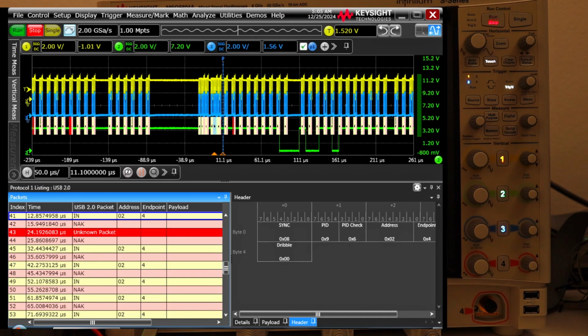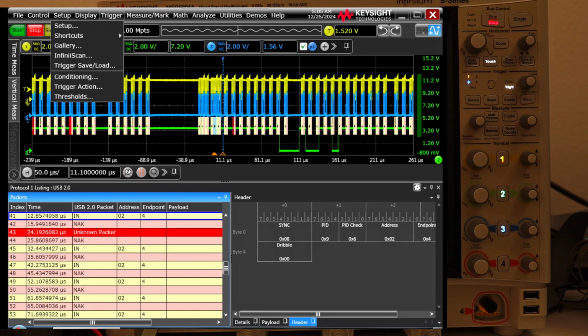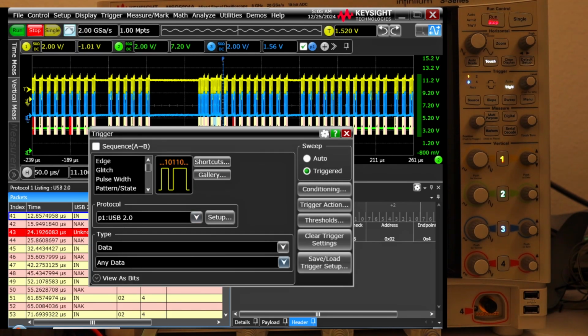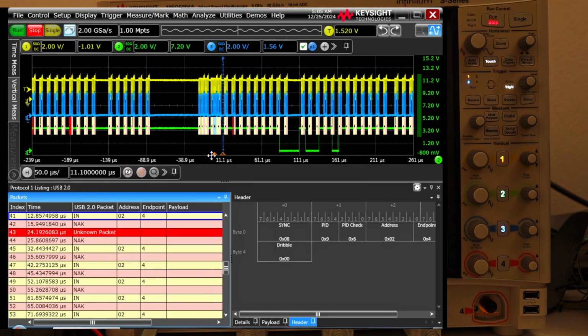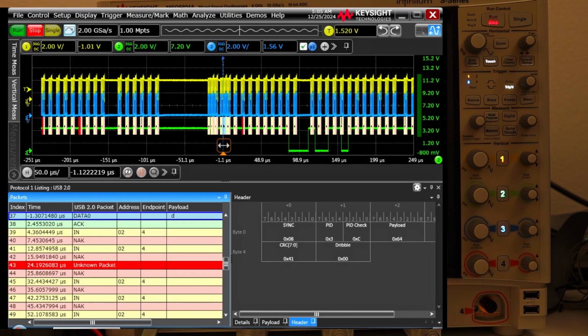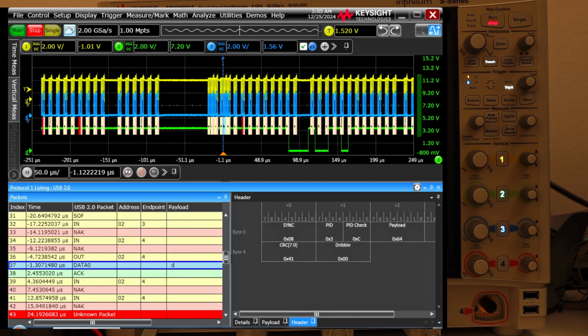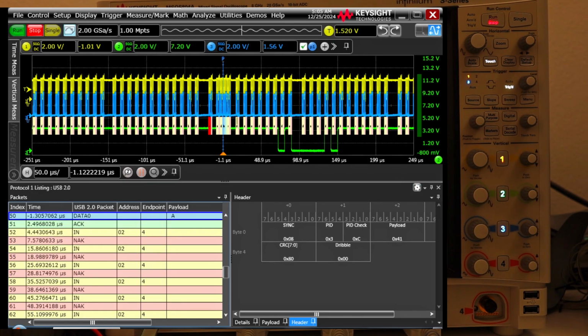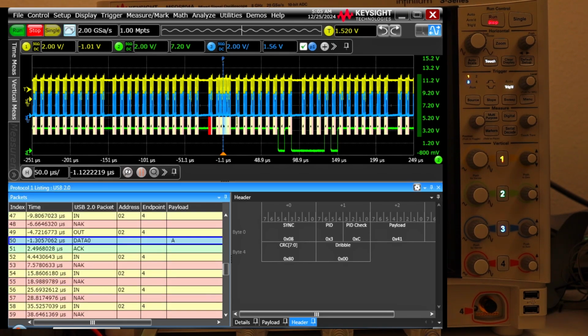Right now our trigger and decode is set for USB and any data packet. So it triggers somewhere here, where it finds the trigger right in the middle, and you see the UART packet being transmitted. So our goal is to find out the packet itself. You see this data 0 is D. Let me transmit the A as well. So we'll do a single trigger, transmit A, and you see the data packet 0 is being received A, and the trigger is in the middle.